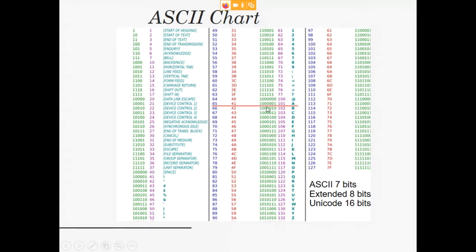So if we take the letter A I've got underlined here, that is 7 bits, so it's 1, 0, 0, and then 0, 0, 0, 1. And so what it would do is you look there and there's 2 1s. So if you were doing even parity, it would count up how many 1s you have, which is 2, which is an even number. And so it would send the parity bit as a 0.